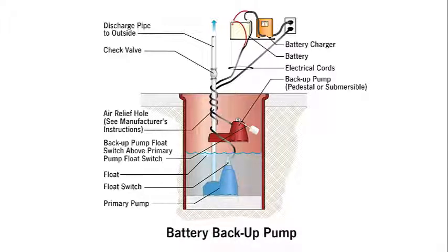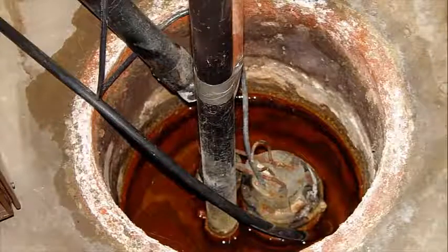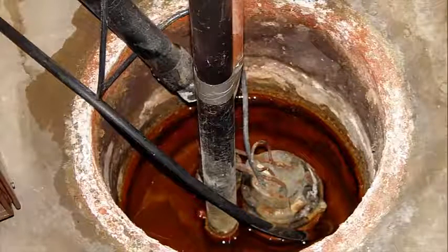This type of pump is often accompanied by an alarm system that provides an audible and visual indication that the backup pump is or has been in use. Water-powered sump pumps are also available and can be used as either the primary or as a secondary backup. Perhaps the most common failure modes for sump pumps are power failure, switch failure, or obstruction, an undersized pump, a frozen discharge line, and old age.